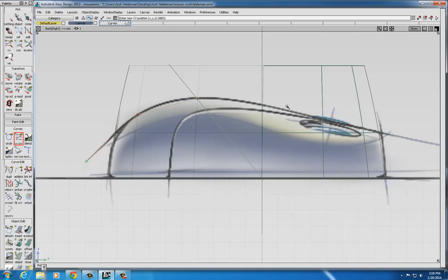Third point, again, somewhere up near the top. The fourth point, which will allow my curve to finally snap in, remember we're using the CV curve method for creation here, is going to be where the center point for the buttons is, where there's a vertical line that's perpendicular to the line I'm trying to draw. Place your fourth point right about there. The fifth point and sixth point are going to be beyond that edge, and they're only there to help us make sure that we've got that curve in the right shape.